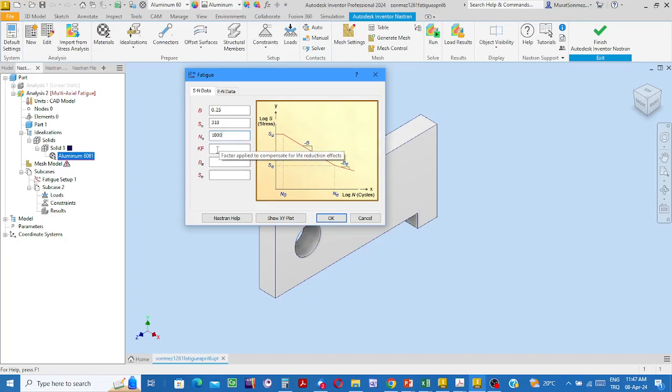The Kf factor is not available. It is not easy to determine the Kf factor. It considers the roughness of the surface and also corrosion over the surface. If the factor is not available, leave the compartment empty. This box is to write the slope of the S-N curve after the endurance limit. Theoretically, after the endurance limit, the slope of this part of the curve is 0. It is a horizontal line.